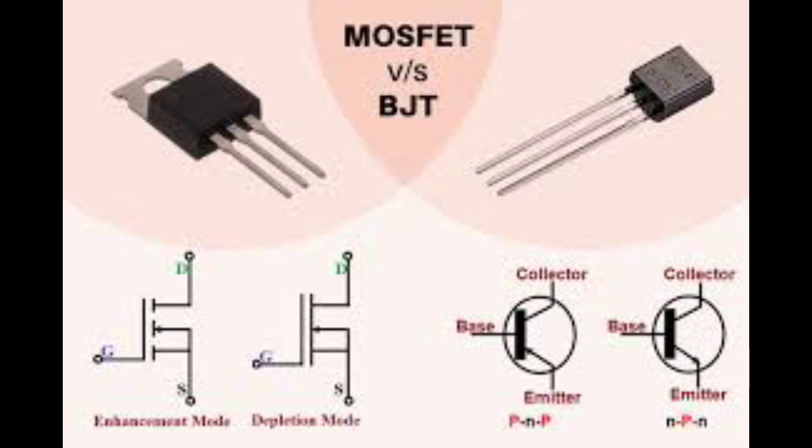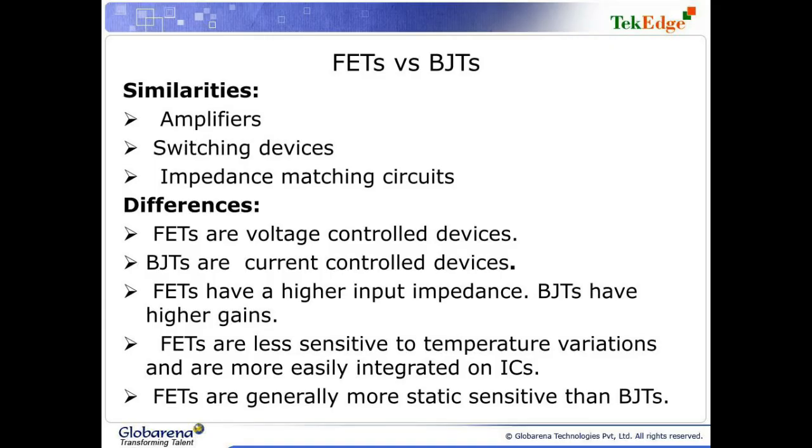Germanium, used in early transistors, for example in the 1950s, has a smaller band gap of 0.67 eV, which makes it more conductive but also more sensitive to temperature changes. Other materials like gallium arsenide are used in specialized high-frequency BJTs, for example in RF applications, but silicon dominates due to its cost-effectiveness and reliability. Silicon is preferred over germanium for several reasons.